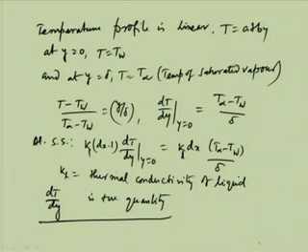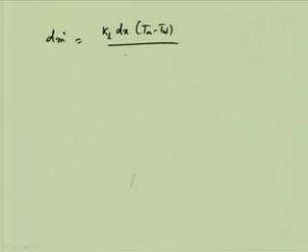Then the change of rate of condensate flow is because of this condensation. So, dm dot, the change of rate of condensate flow, is happening because of the heat transfer, and that heat transfer rate is K L into dx into (T infinity minus T w) by delta, divided by the latent heat of condensation or latent heat of vaporization.